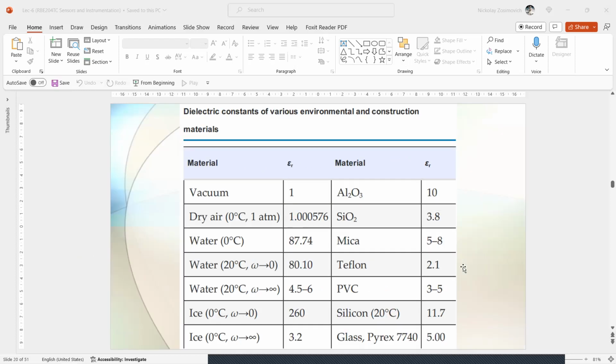The lower limits of linearity, stability, and accuracy of these precision sensors are set by the air humidity. What does it mean? It means the water vapor in the air might condense in edges and small gaps of the construction, like capillary condensation.